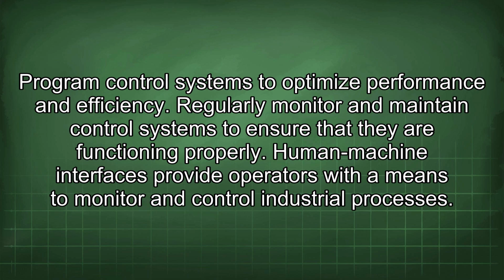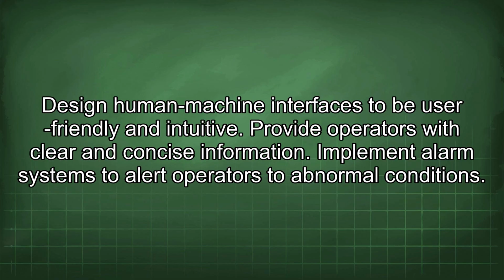Human-machine interfaces provide operators with a means to monitor and control industrial processes. Design human-machine interfaces to be user-friendly and intuitive. Provide operators with clear and concise information. Implement alarm systems to alert operators to abnormal conditions.